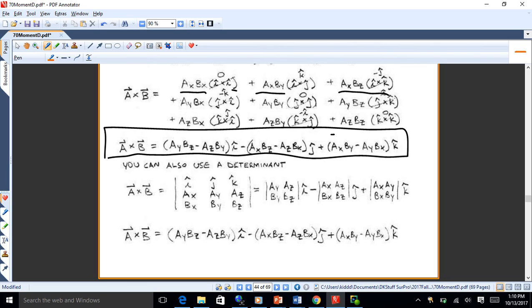As I've mentioned, if you need that formula, it's on the formula sheet, in the left-hand column right at the bottom. When you do a cross product, you find the torque. Do you take the displacement first or the force first? Displacement first. It's r crossed with F, and it has to be that. That formula is shown right up above, so M equals r cross F.